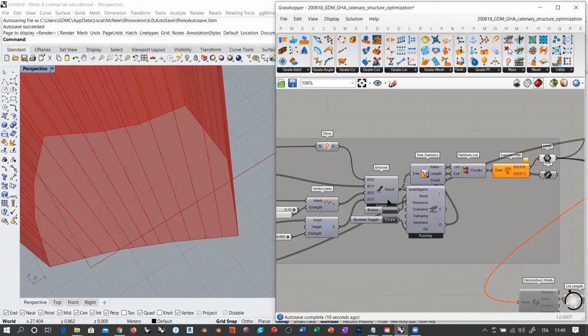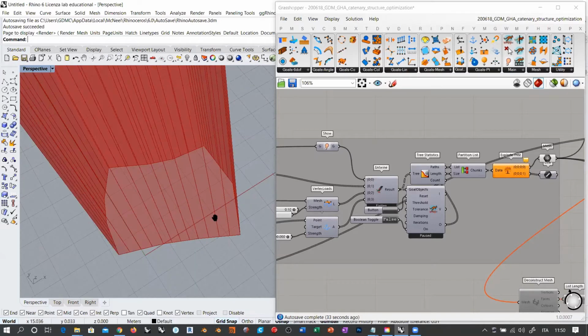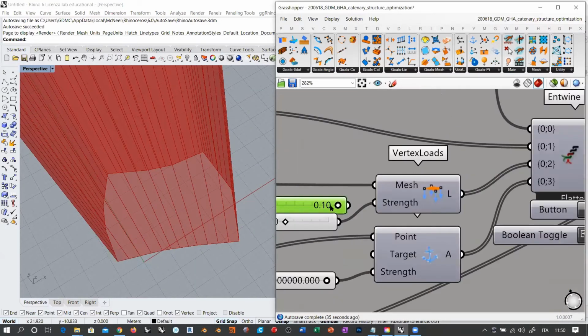Oh, you see, for example, right now I have eliminated the elastic property, or got back to a very soft body, actually, and I'm still applying 500 kilonewtons to this object. So the deformation is now something like this. Of course, there is a scale factor that is not being respected. So I will go back to 0.10.